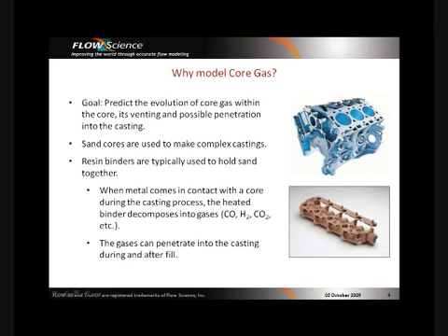The core gas model simulates the behavior of these gases that appear in sand forms from organic binders when the sand is heated by the metal. These gases can build up enough pressure to blow gas into the liquid metal, thereby causing porosity defects. The model describes the formation and flow of these gases into the porous cores and mold, the pressure distribution inside the sand, and the amount of gas, if any, that escapes into the metal.